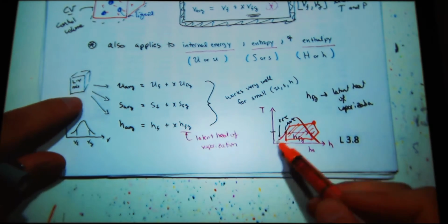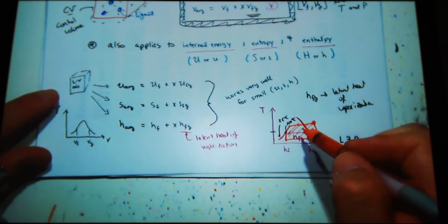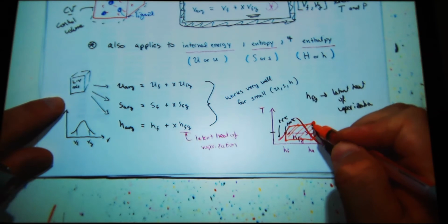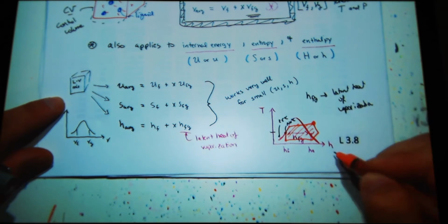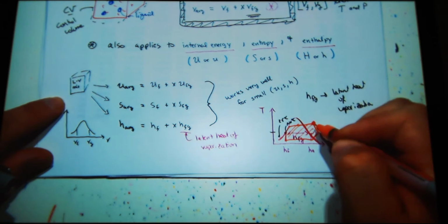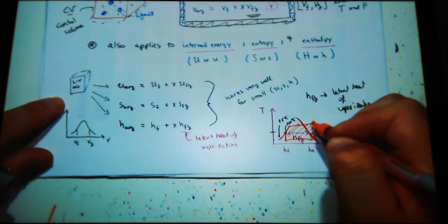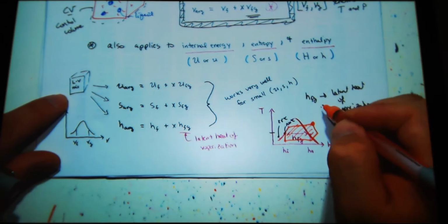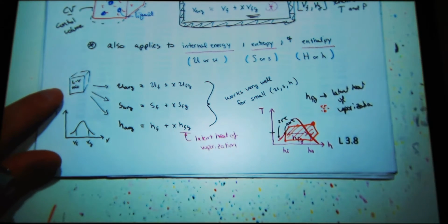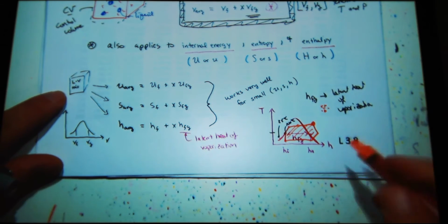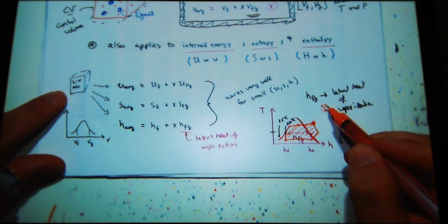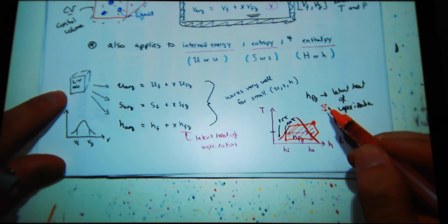They'll plot out the properties they expect and then update the temperature. Now, they won't use enthalpy, they'll probably use specific volume. They'll be plotting the pressure and temperature against specific volume at that point. If they suddenly start getting dots out here, they know to hit a red button to shut it down, because they're way outside their operational regime and things are going to get damaged.